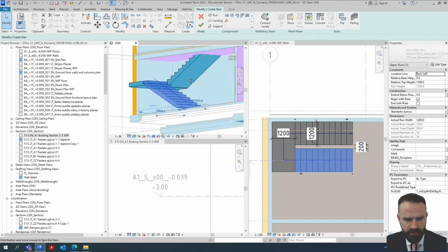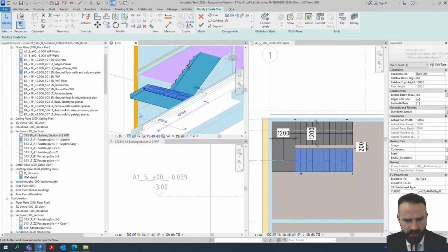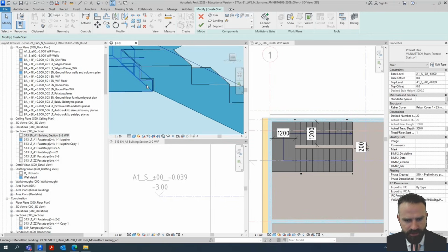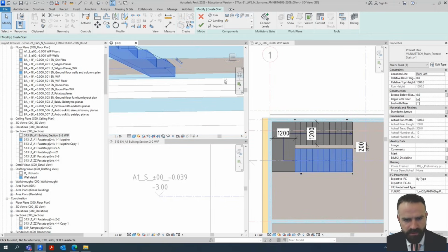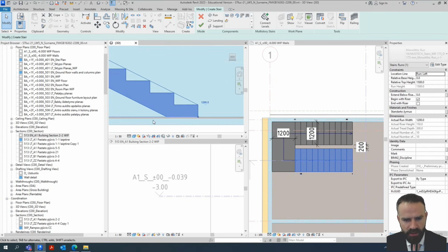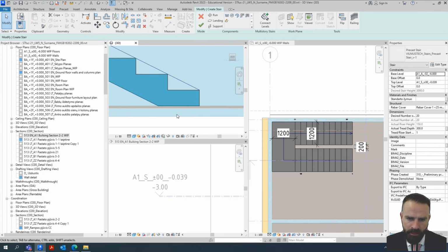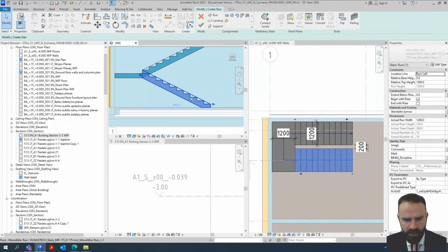I can check it out and rotate it in 3D model also, and I can see how they are connected. So connection in this location is okay. Now connection on this location. So I would like my stairs to go on the bearing part of my floors, or I need to have some specific foundation. So I select the last element here and use extension below rise base. So in this case, I will write -100 and I will use begin with rise. So it should have the check mark.